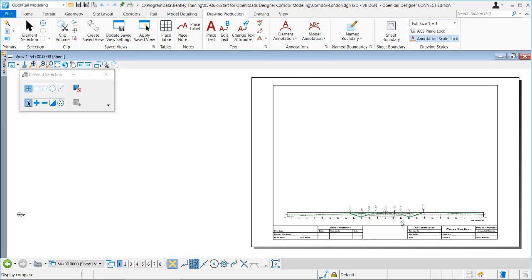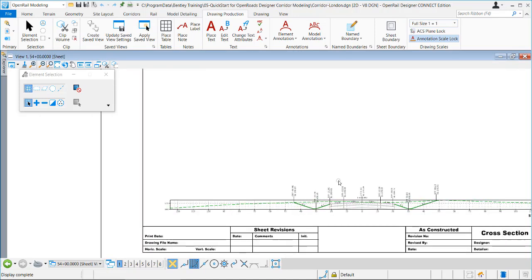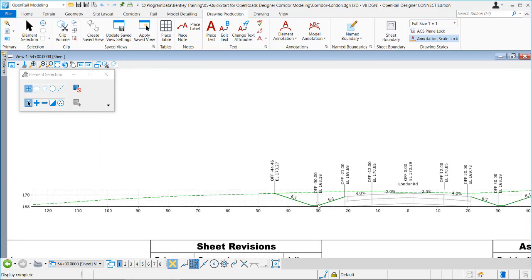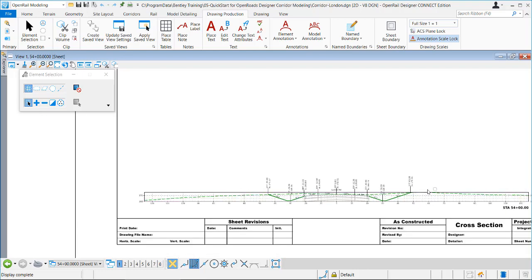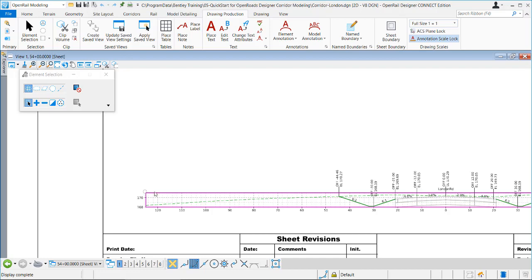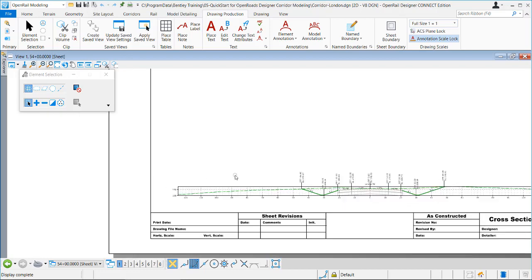Okay, so it took us to the last cross-section that it created, but this is a good one where we can see that it's taken the bottom elevation among all those, and that's probably the bottom of this ditch, and it's gone down, and we had a datum elevation of 1 foot, so it took us to 168 at the bottom. And then it takes the highest elevation, which is probably up here on the surface, and it goes up. We're probably at 173 there for our top elevation.